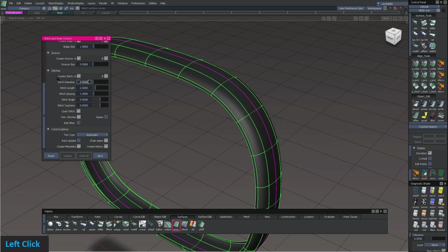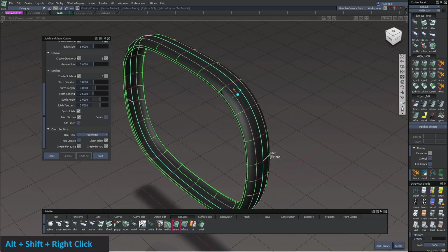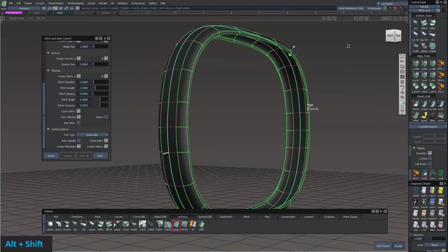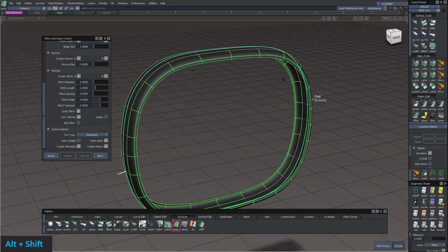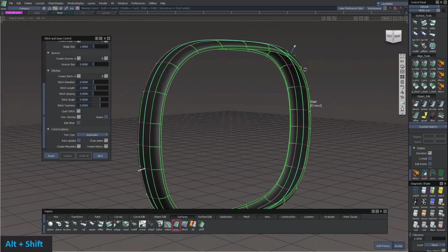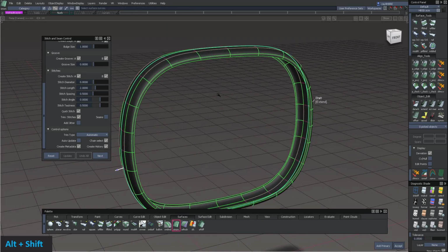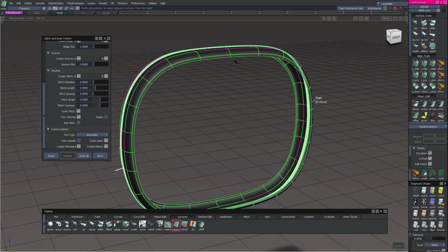which later I find is a little too small. But remember to just play around with the settings, and maybe certain things look a little better, especially if you change the bulge size or eliminate it. It really depends if it's very soft or very hard leather. It really helps put some detail into the model. So once you actually select it, you're going to see that arrow. Make sure it's pointing out. And then when you click enter, it's going to actually develop all this stitch and seam.